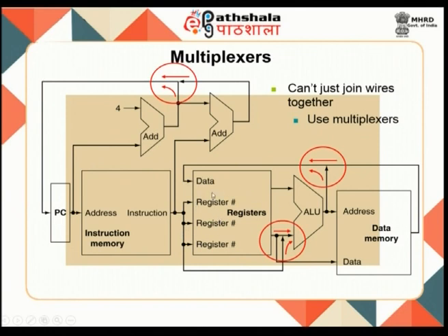So, this is the register file, you store all the register values here, and then you go ahead and do the other operations. So, it passes on to the ALU unit for arithmetic operations, and then it passes on to the data memory for your load or store instructions, and then you have to pass on the result if it is a load instruction.